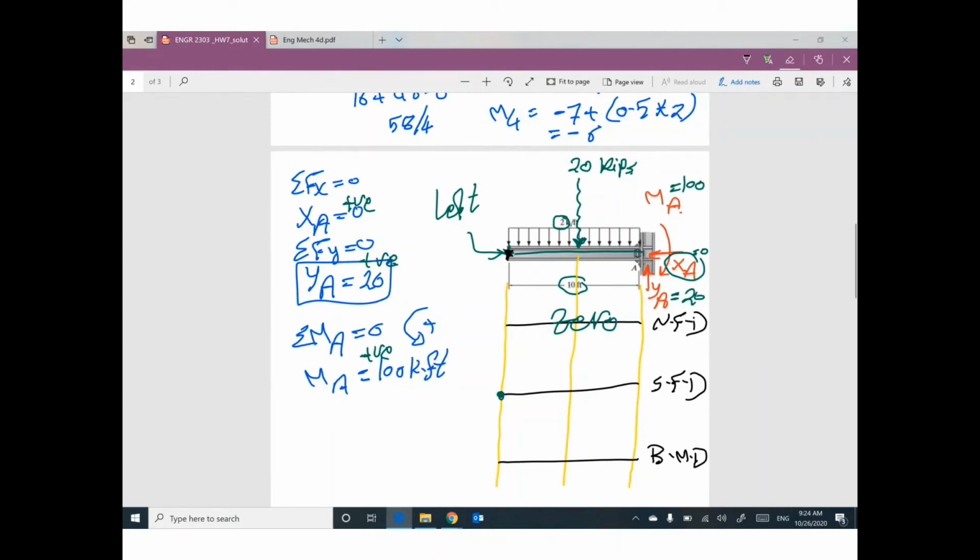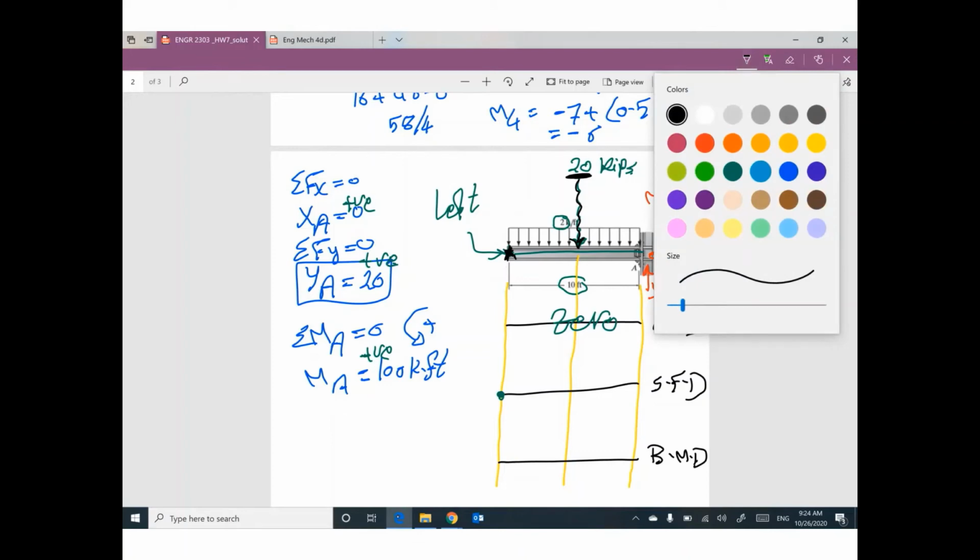So one of you will say, hey, we have the uniform distributed load. No, I'm talking right now about this equivalent, 20. Please forget the distributed load. Is this equivalent force right now at this end? No. So do you have any force at this end? No. So I will not go up or down. Your value is 0.